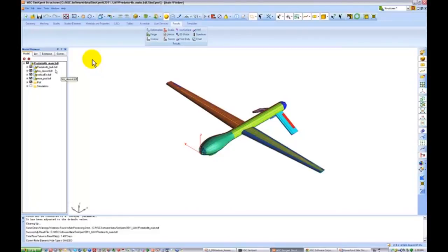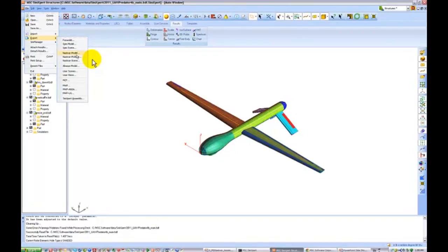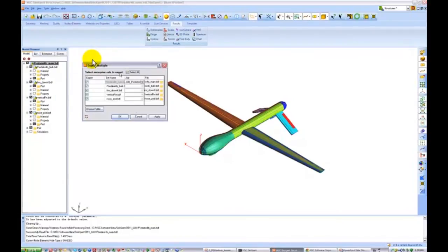And this model, using the model browser, you'll see here that this model is actually a main include file. So if I go and browse to it, you would see that this only supports includes of the 4 files below. So when you read in models in SimXpert as a natural way with the model browser, you retain the relationship to these subfiles. So these little files here are all individual buckets in which each of the components are maintained. If you import your models with any other UI, you will actually end up with a monolithic model. In this case here, if we make a modification of the mesh, we have the ability to maintain this relationship, and we can actually export Nastran and multiple.